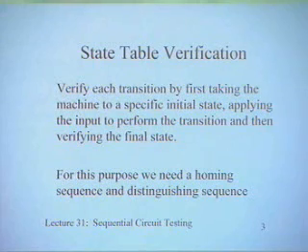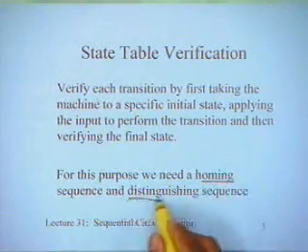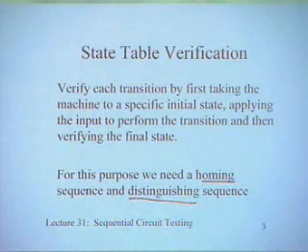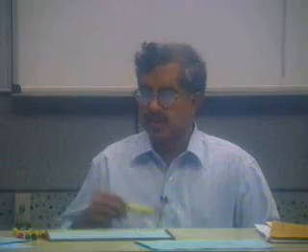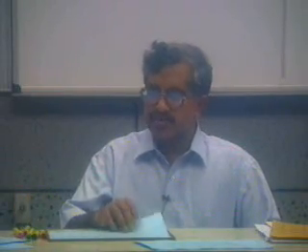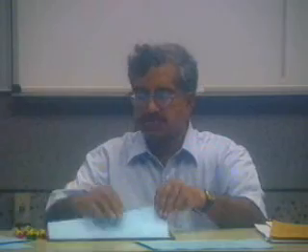For this purpose, we need two sequences. One is called a homing sequence, another is called a distinguishing sequence. We have studied about distinguishing sequence before, so today we will talk about the homing sequence. Let me first define both of them.